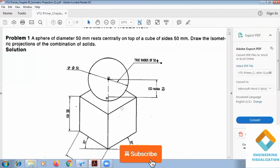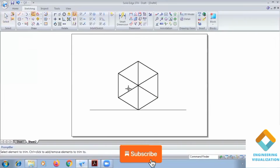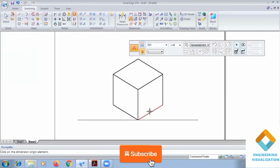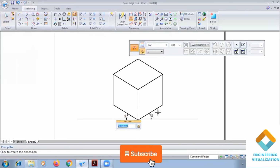But guys, you know that the sphere will be constructed with the actual scale, but the cube we need to convert into isometric here. Okay, so that is the important thing you should remember. You can keep it like this. Then you can show the angle. And this is one of the basic first problems of the isometric projection, guys, and this problem can be asked in the exam.